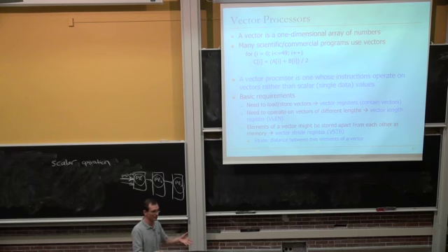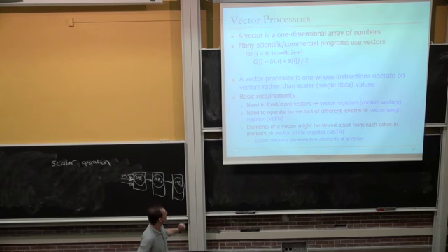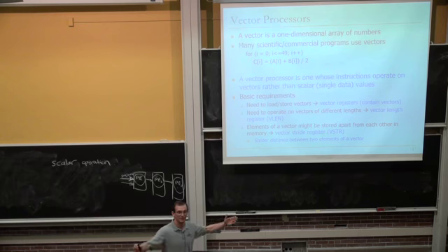But registers, as you know very well by now, exploit the locality in programs, locality in data. So we would like to have registers. And we would like to provide the vector registers, which can store multiple data elements. So you need that. You need to be able to operate on vectors of different lengths. You don't always have vectors of a fixed length. And you don't want to design your machine so that you can operate only on fixed length vectors. So we have a vector length register which the programmer can change dynamically. Well, with code, basically.